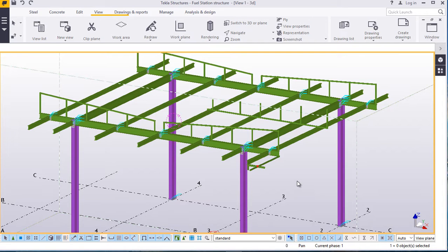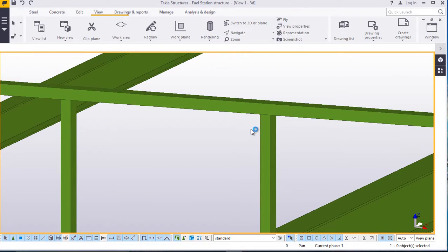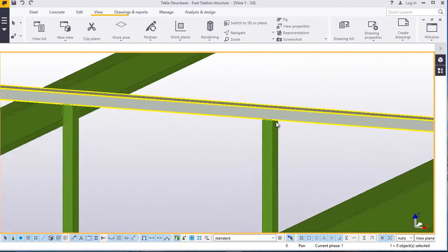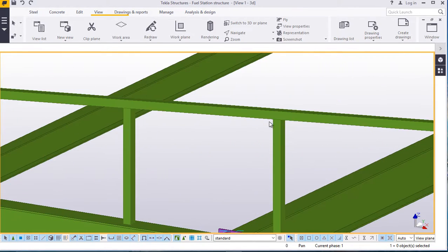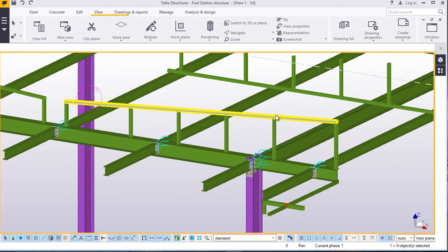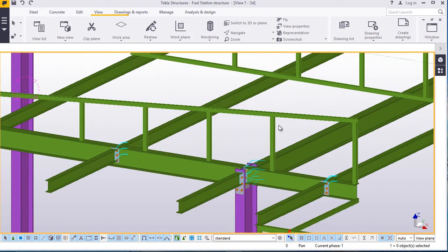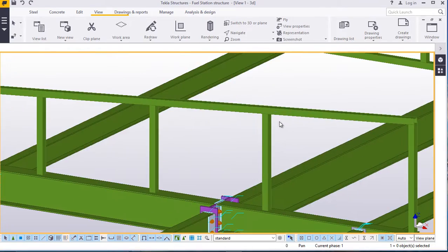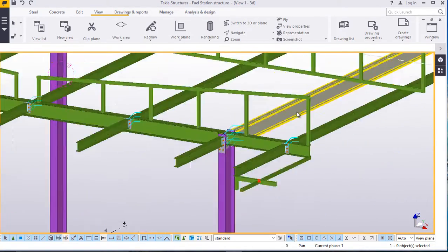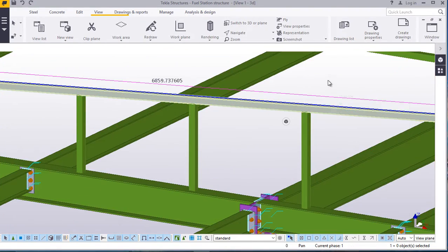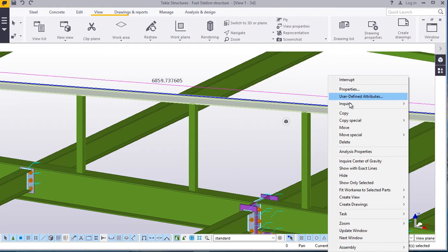Let's kick off here. First of all, as I promised you in part 1, we'll do some rectification here. So the first rectification we are going to do, we are going to reduce the height of this truss. We'll shorten the struts, the height of the struts. Now we'll click the top chord and come to move.